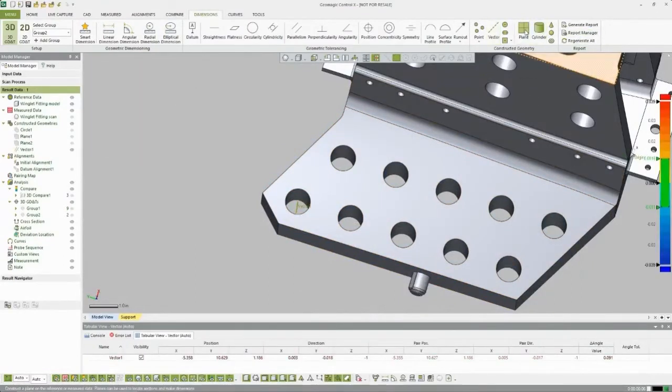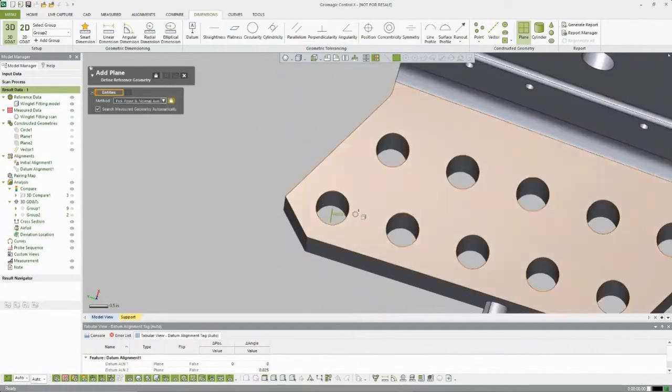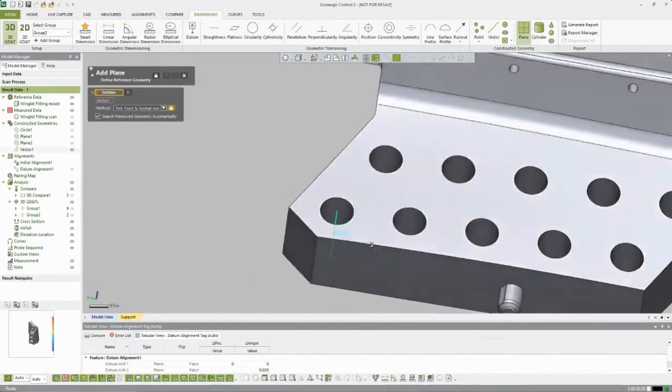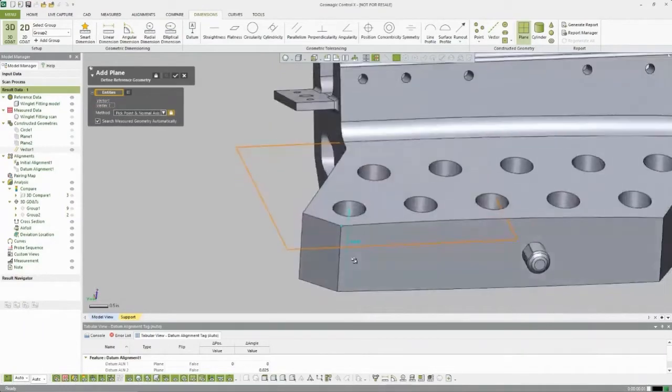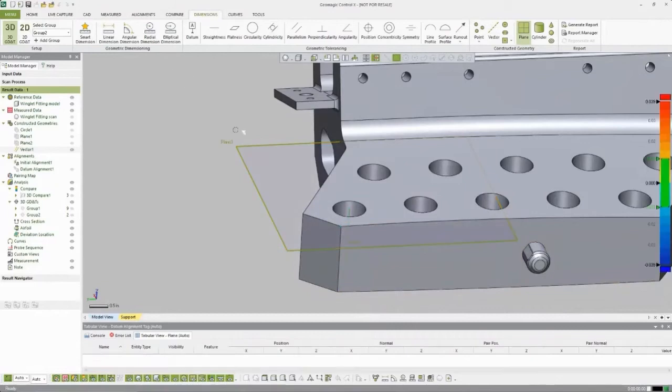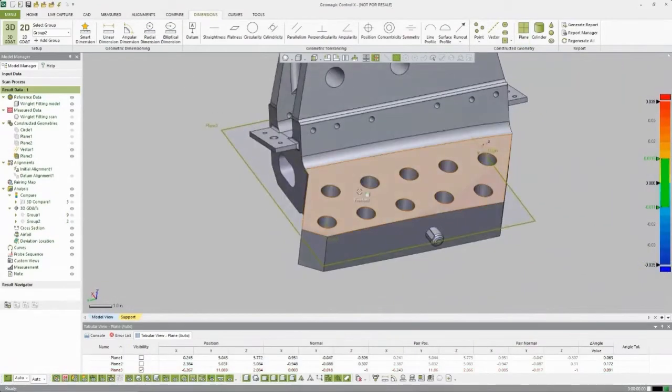And then I'm going to choose a plane that I'd like to do my cross section on. And I'm going to work with the pick point and normal axis method. So when we click the axis, I'm just going to click a point. I can click any of these here. And you see that it's going to create a normal plane to that axis. All right, there's my sketch plane. So that's the plane I want to use for my cross section.